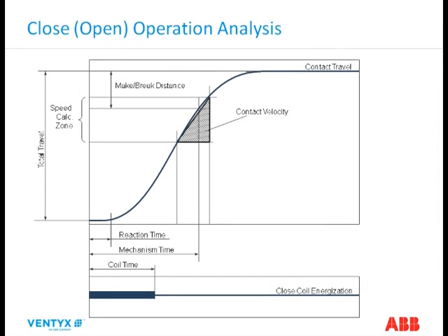This is just showing, depending upon the type of sensors that you have available on the breaker, you can actually directly monitor the contact velocity. With a relay, you can capture the total reaction time to breaker opening time. It gives you an indication of the health of the mechanism, but doesn't give you the same level of information in terms of the contact velocity, which is actually important to know in terms of the interrupter wear. But this is the type of data that we're looking at and processing as a result of the monitoring and the sensor technology that's currently available.